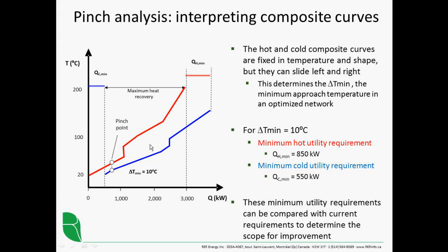So there's a greater driving force for heat exchange between the hot and the cold processes. That facilitates heat exchange, and it means that we can use smaller, less costly heat exchangers, but it also means that we're going to have more flexibility in how we associate hot and cold streams for heat recovery because there's a bigger driving force between the two different streams.